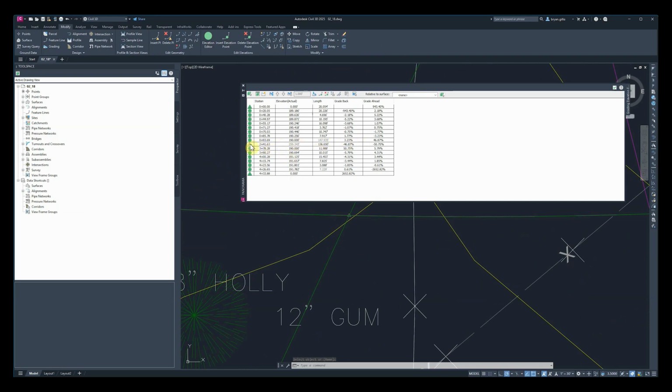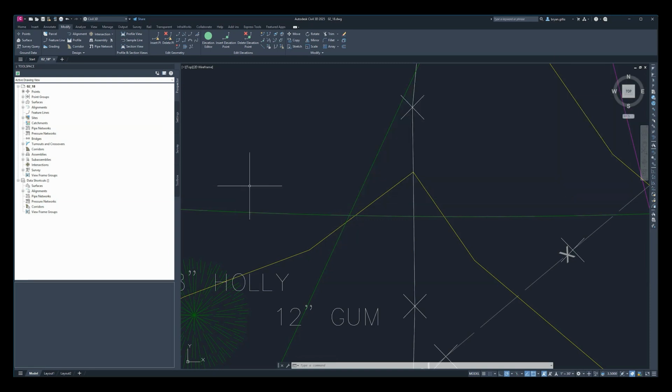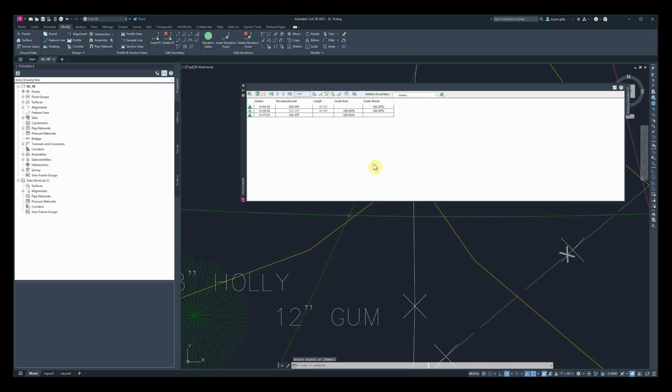We have an automatically linked station point that's created from that intersection. So it's going to be there. If it's too big to see it here, you can do the same thing, and instead of selecting our previous one, we can select the line we just created. We only created 2 points with a single grade along the whole thing. That intersection is going to have a point right there created as well. So again, we get to see how when we work with survey sites, it ensures that there is integrity between our different features within that site to help eliminate discrepancies, or in some cases quickly identify some of those discrepancies.